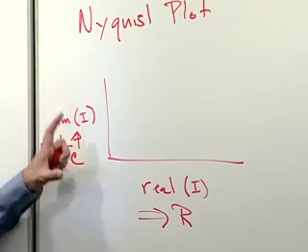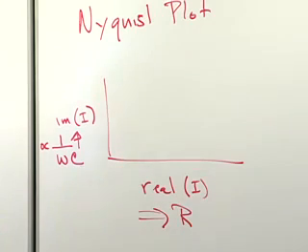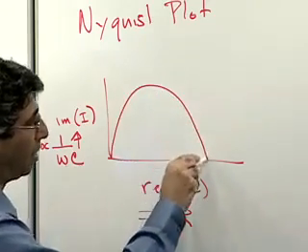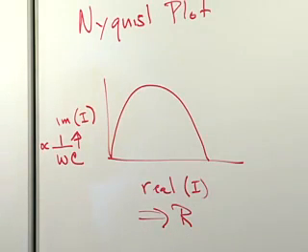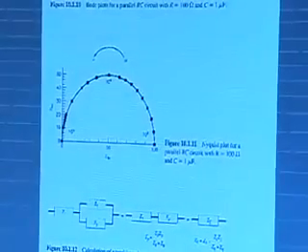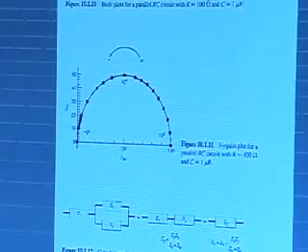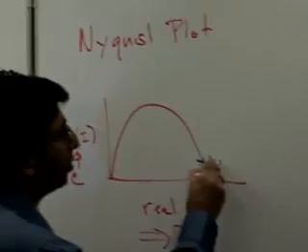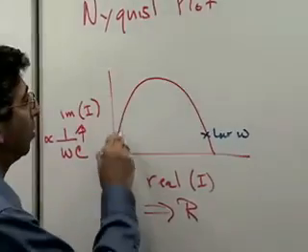Okay, and so if we have a pure RC circuit, nothing electrochemical, but a real live resistor and a capacitor in a circuit, then you'll get a plot just like shown on the PowerPoint. You get this nice semicircle here, where the total resistance of the circuit can be determined by where this circle or semicircle impinges on the resistive axis here. The way this is working is we're moving from low frequency to high frequency.